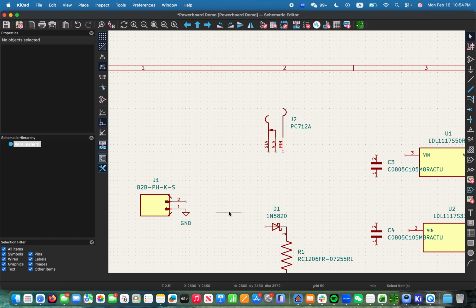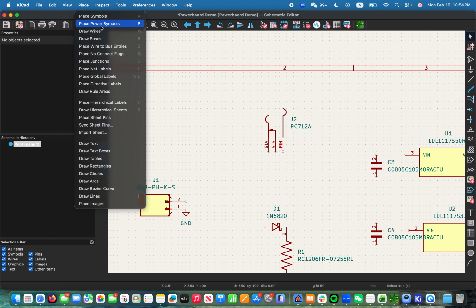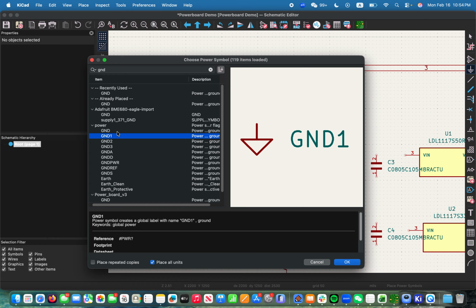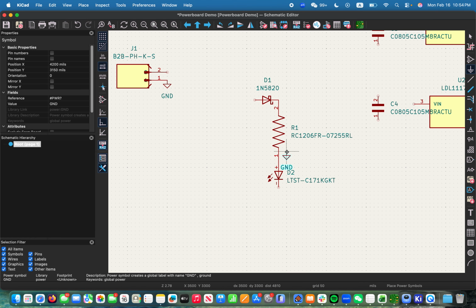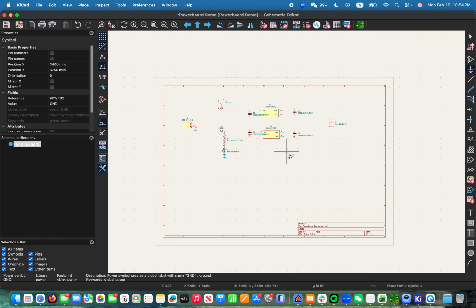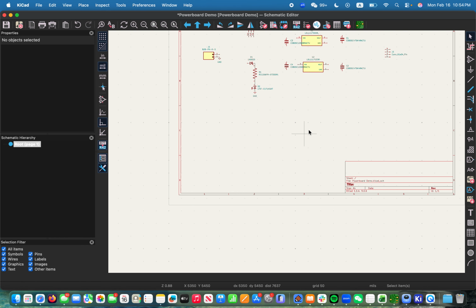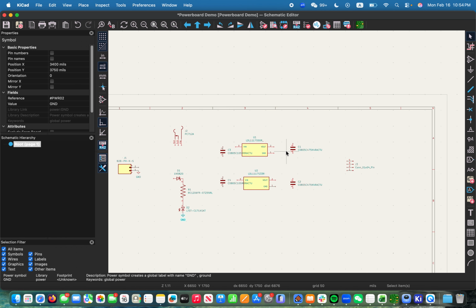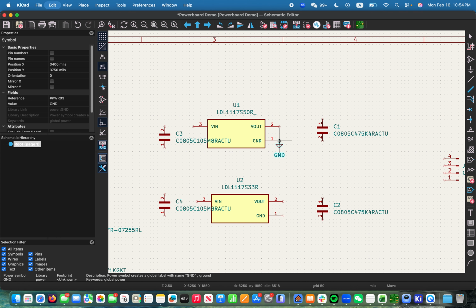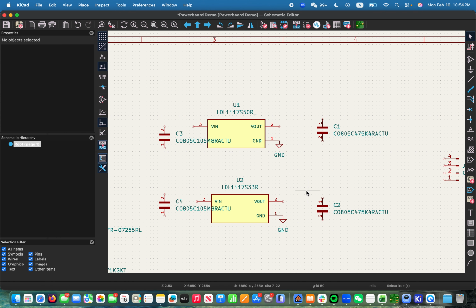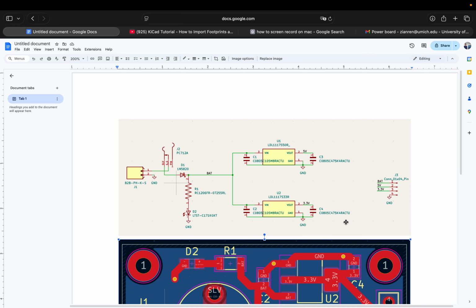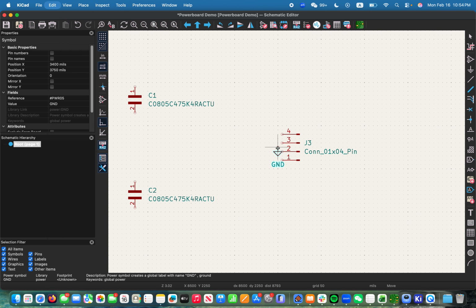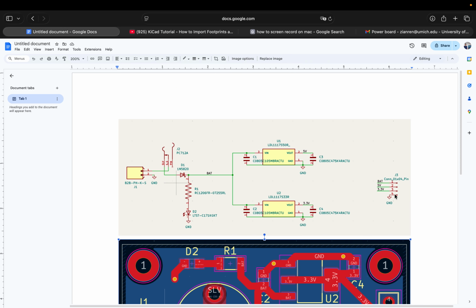Let's make sure that we're also grounding everything else that we need. That's going to be down here by this LED. And then I believe that ground needs to go here and here. So let's grab this ground, copy it, just Control C or Command C if you're using a Mac, and then paste it here, and then paste it here. So we've got 1, 2, 3, 4 grounds, and ground on pin number 4 of our J3 connector. J3? Yeah, on our 4th pin here.